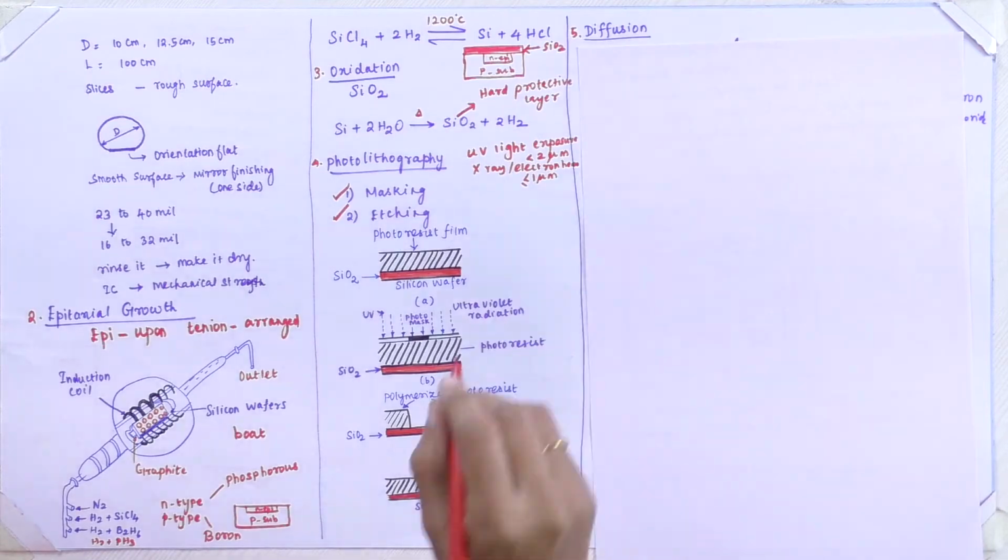Next comes the fifth technology, called diffusion. Diffusion is nothing but the addition of impurities. As I said earlier, the SiO2 layer from oxidation is used to prevent the impurities from going beyond into the N epi layer or the P substrate, whereas the diffusion layer is different. We all know that pure gold is not used for an ornament, so we have to add some material like copper. It's like adding impurity to make an ornament.